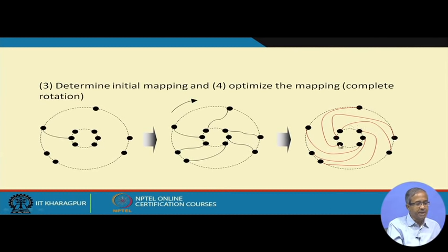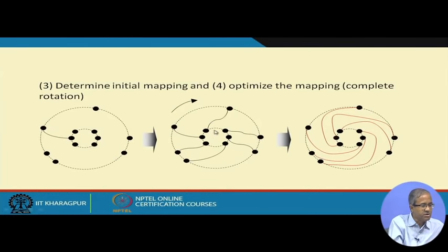You see, this is a bad rotation. If you rotate this pin to here, then you have to connect it using long wires. So, you try to rotate the pins in a way such that the interconnections become simpler. If you rotate in the wrong direction, then the wires will become very long. So, you find out the optimum angle of rotation for which the total of your interconnection lengths is minimized. This can give you a good solution. Maybe if you rotate it a little bit to the right, it will be even better, but this is a bad rotation.